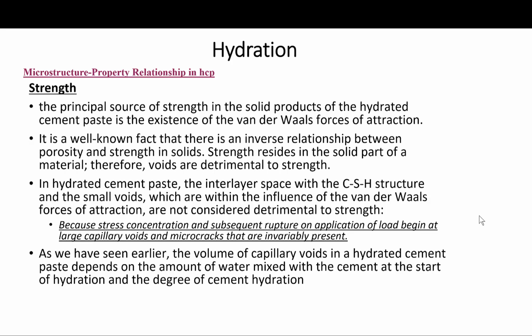So the small crystals of the calcium silicate hydrate, the calcium sulfoaluminate hydrates, and the hexagonal calcium aluminate hydrates possess enormous surface area and adhesive capability. So these hydration products of the Portland cement tend to adhere strongly not only to each other, but also to low surface area solids, such as the calcium hydroxide or the anhydrous clinker grains that remain within the hydrated cement paste, and also the fine and coarse aggregate particles.